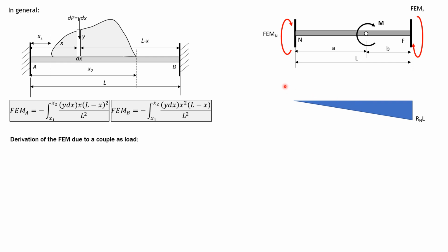Then the moment at the near end, which we assume positive, like the one shown, fixed moment here. Then due to the load, we have another positive moment. And so for the first part, EI theta NF equals 0. So area above equals area below.